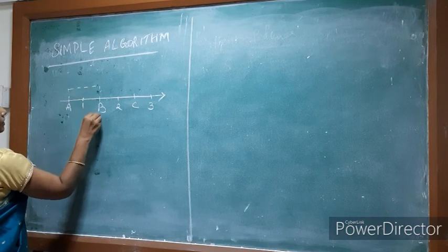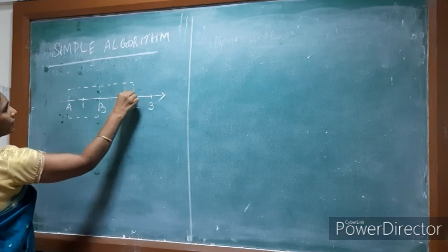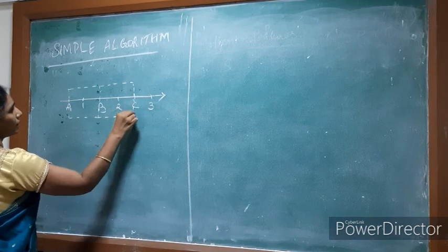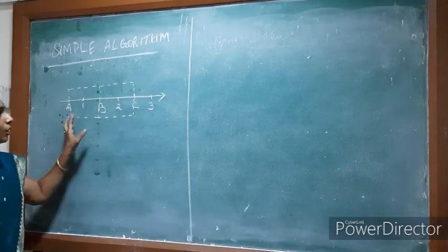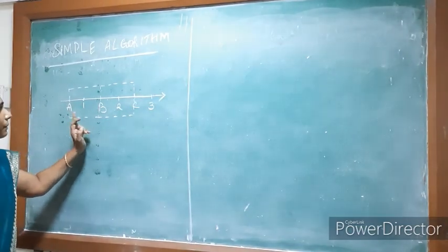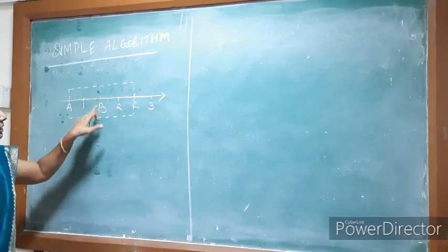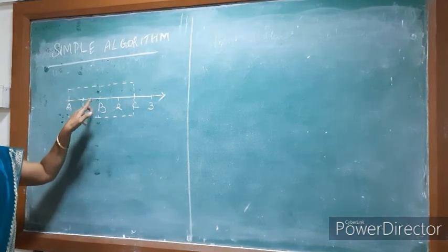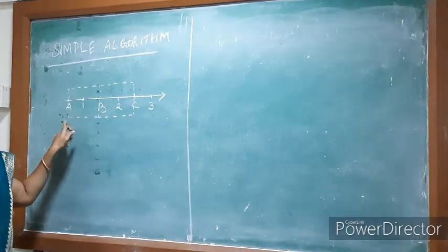Just to recollect what we have seen in the previous classes, we were referring to staggered grids. So all the parameters, that is pressure, temperature and other turbulence quantities, will be measured at the central node except for the velocity. The velocity alone will be taken at the face, that is across the face of this control volume. So this is the first control volume that I have marked.